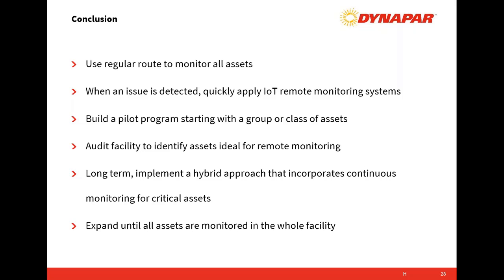One of the things, Derek, I'll add on that is we've even had people look to add vibration data as almost another input in terms of control. Setup is a good example. We had a punch press operator catch a defect. We were monitoring the rotating equipment mainly for bearing defects and alignment, but in this case we were grabbing some data when the punch press was running.